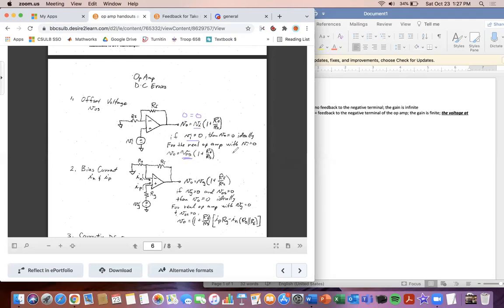So a lot of the times they give us plus minus 5 millivolts or something like that. And so what you have to do is, if they say your voltage source supplies 0 volts, they'll usually say the voltage generated is 0 volts. However, the voltage offset is 5 millivolts. And if you know the voltage offset is 5 millivolts, that means it can go in the positive or negative direction by 5 millivolts here. And so then you just plug in 5 millivolts here.